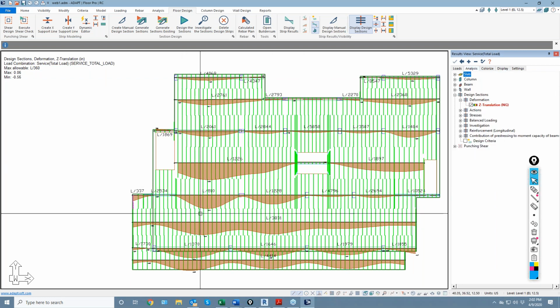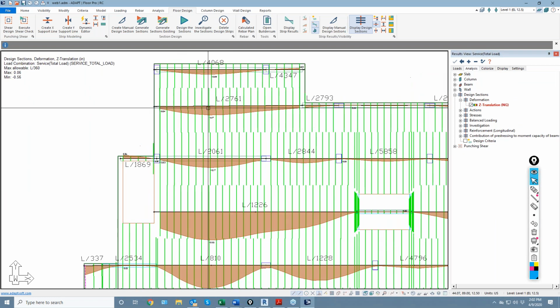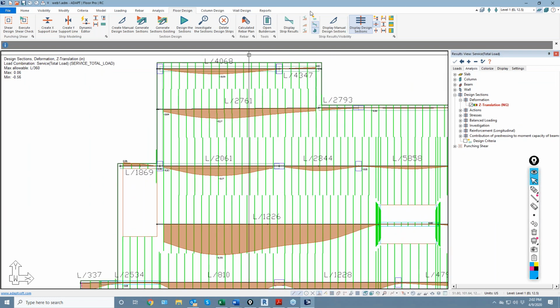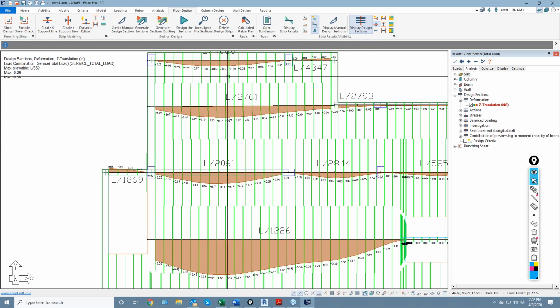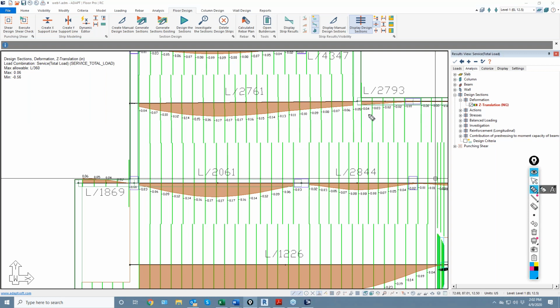Some of these results are actually, they don't really apply, and I'll explain. So when we calculate this strip deformation, we take the maximum integrated deformation on any design cut divided by the span length. So here the span length is from 0.1, there's 0.1 to 0.2. So that's truly a span.